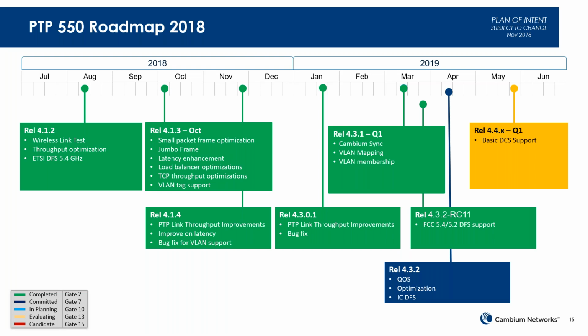So for example, if I'm running on 5.8 right now, I have high interference, but I found 5.1 is cleaner, and I will move my channel from 5.4, 5.8 to 5.1. And also when I make the change, it depends on the real situation in the 5.1 spectrum.